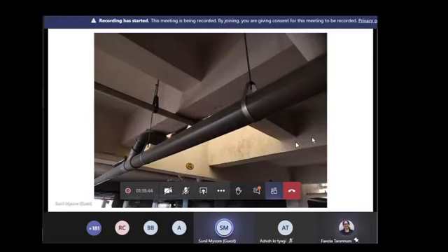So this kind of arrangement is possible. In very, very rare cases, a Y will not be possible, where there is no other option. You have to put a T and somehow allow the movement using a clamp. If somebody is interested, we can go into detail about this, but I don't want to spend more time on how much stress builds up and what the friction force will be. It gets into a lot of academic discussion, which is actually of no consequence.